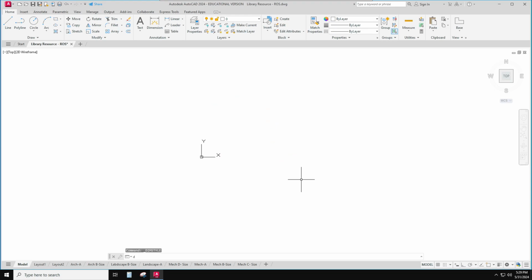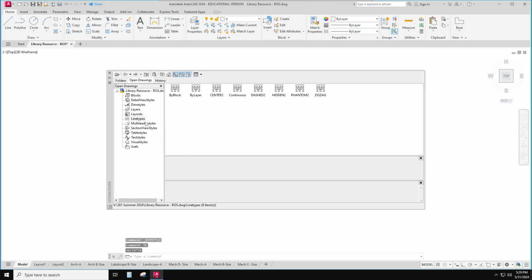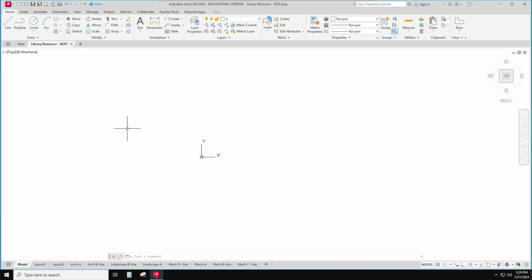If I were to type DC for Design Center and look at my Dimstyles, they're all there. And if I start a new drawing and need one of those, I'll just hold my mouse down and pull it into the drawing. And instead of doing all that setup work again, I'll have just copied in what I just did. Okay, so there you go. That is your Create New Dimstyles demo.